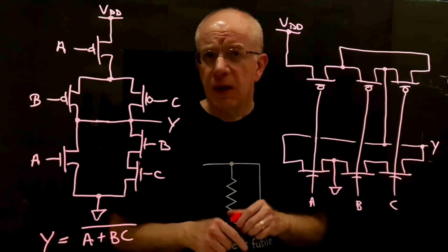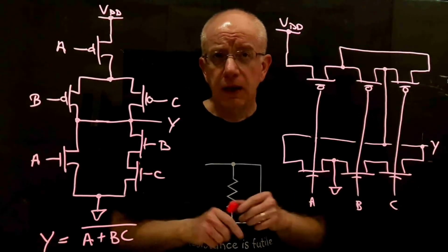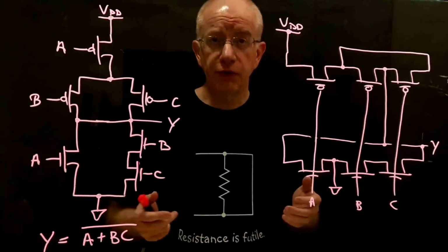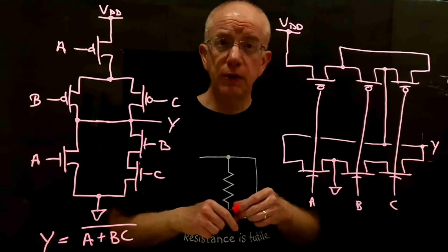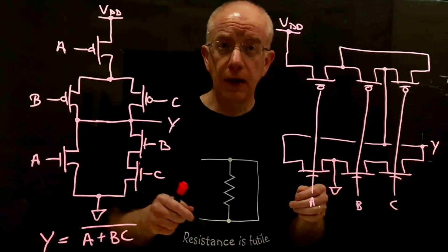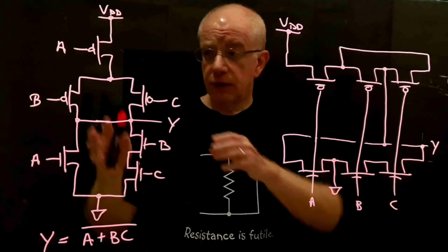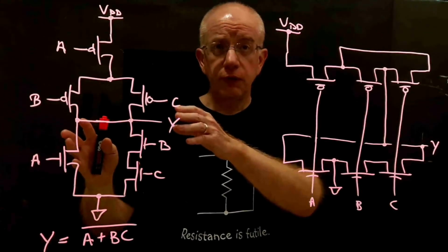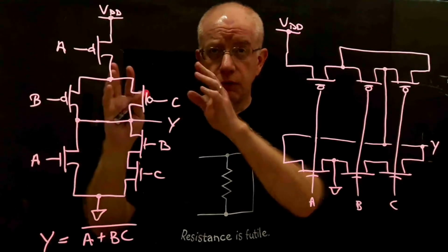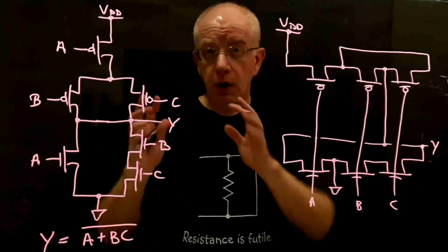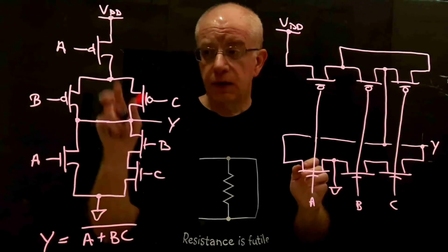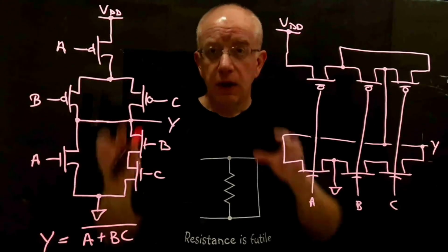The name Layout-Driven Schematics is one that I took from something that's popular in some CAD tools, especially for doing things like mixed signal layout or analog layout, where you've got a schematic and these transistors are just gargantuan. They are very high W over L transistors, and what will happen is you draw on the schematic, and the automated layout tool, which is supposed to be a big help, will take this transistor and stack it.